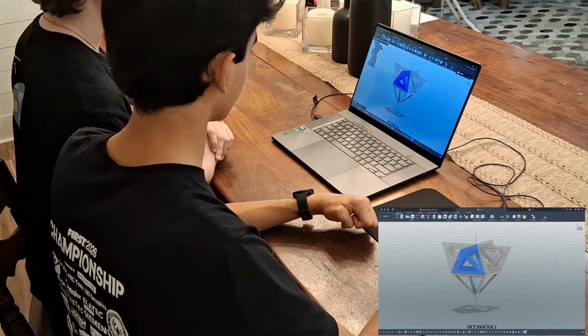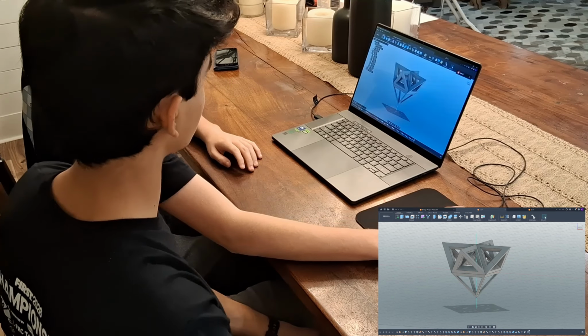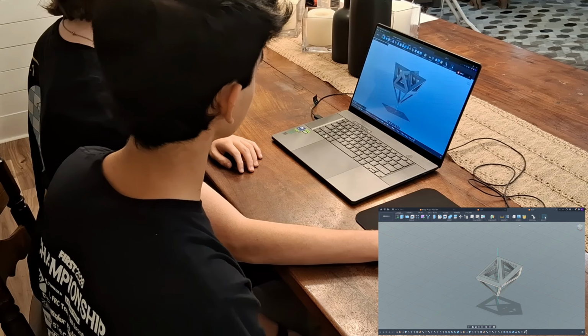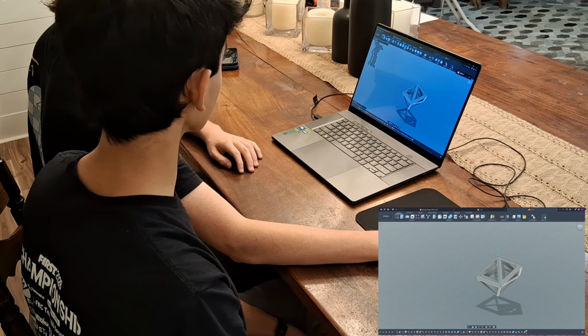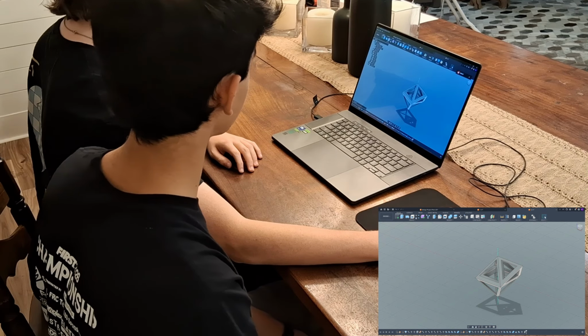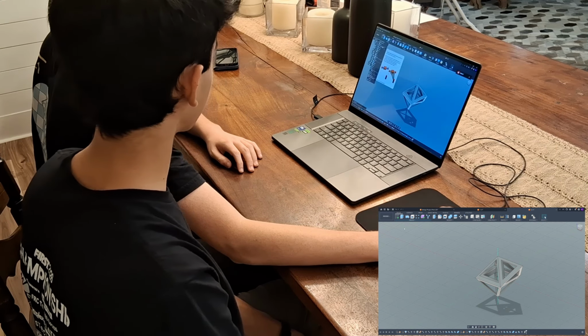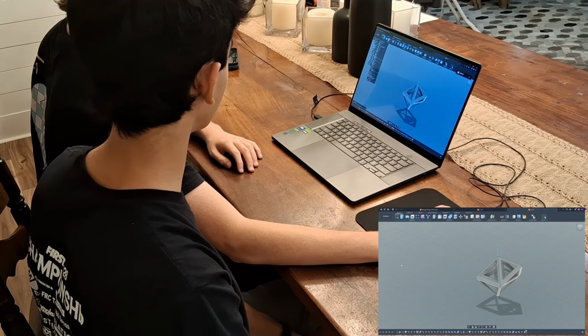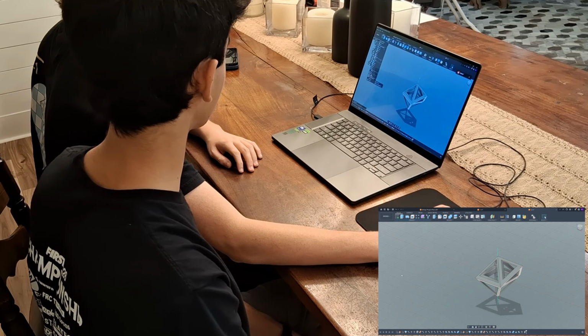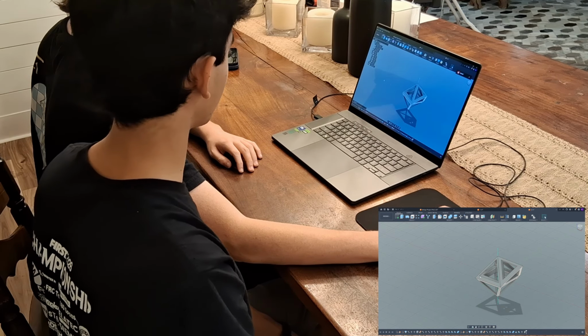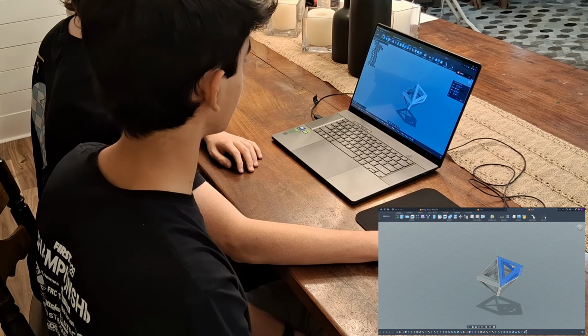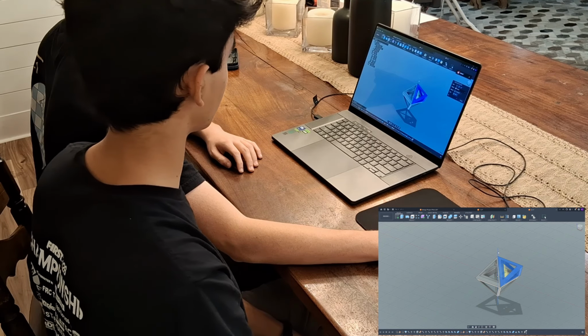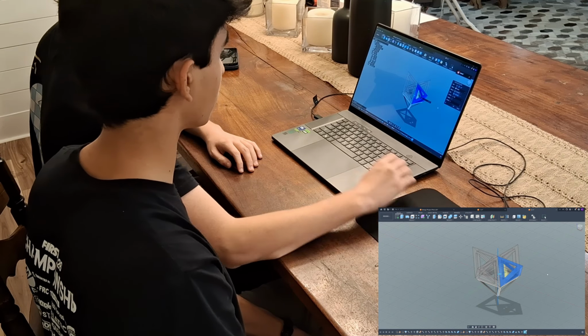Right. Okay, just give it a second. There you go. So go to create and find your circular pattern. It's at the bottom. Yep. Go to pattern. Oh, pattern. Yeah, there you go. Yeah, circular pattern. Click on your object and then find your axis. Yeah, make sure you already have 4, so just click OK.